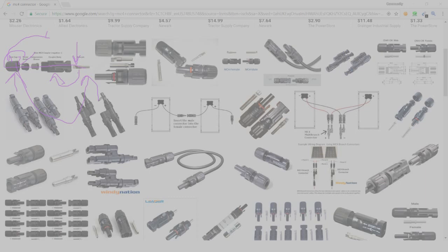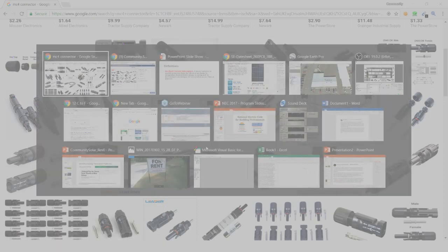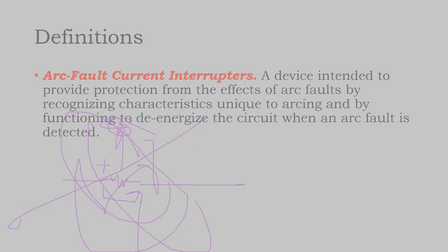And lo and behold, my experience is it's the MC4 connector that is the most common point of failure. And so you have a poorly made up MC4 connector, and rather than connect to ground, you have a positive and negative side of your cable, and every so often either current doesn't flow or you get electricity arcing and still flowing, but that can produce heat and smolder a cable and start a fire, and that's obviously dangerous.